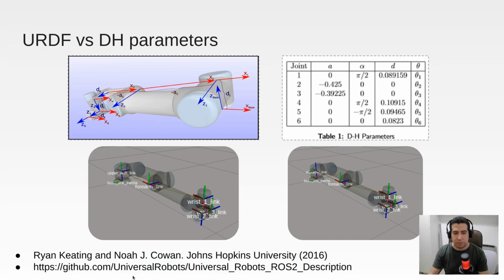And also, actually, the inverse kinematics that's in this PDF here does not work with the URDF that's provided by Universal Robots. So I just had to make some minor modifications to some frames and some math to fully work with the URDF that Universal Robots provides.